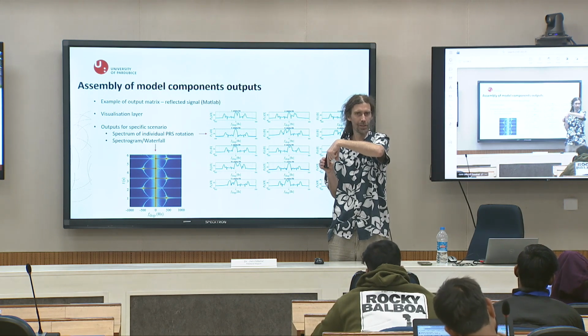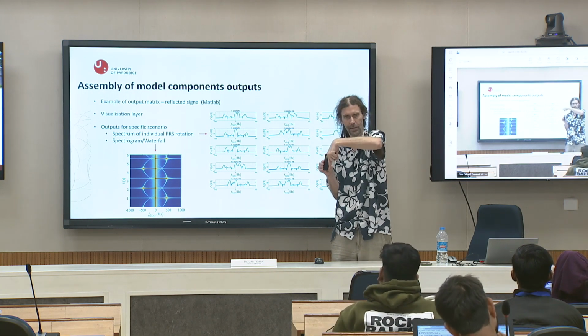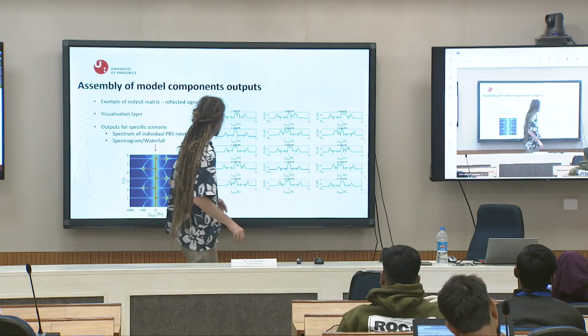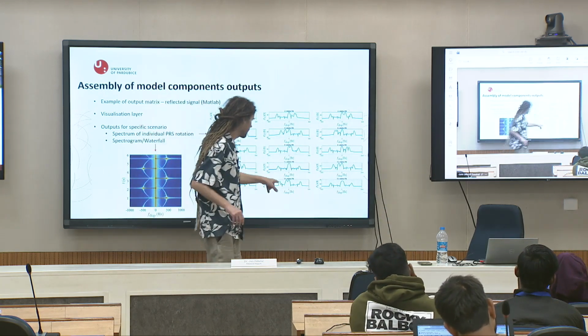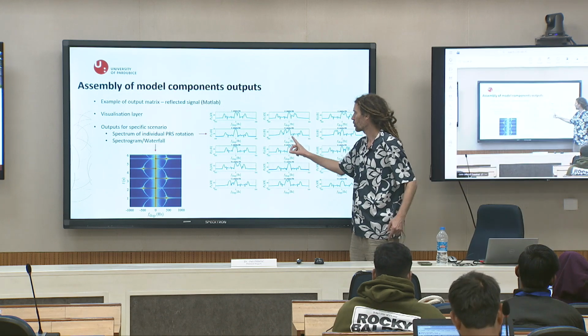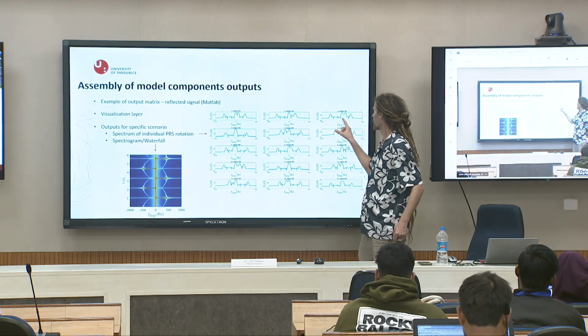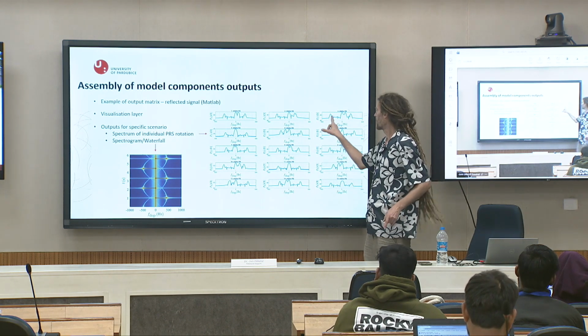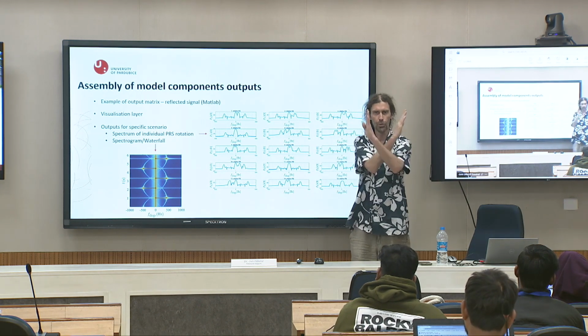This main lobe is always hidden under the tower. This second one is always after 120 degrees if you recompute to time, but it depends on the sampling frequency and all these things. But normally, all three blades are visible and this is 0. So this main lobe is always the same, and these three are moving.